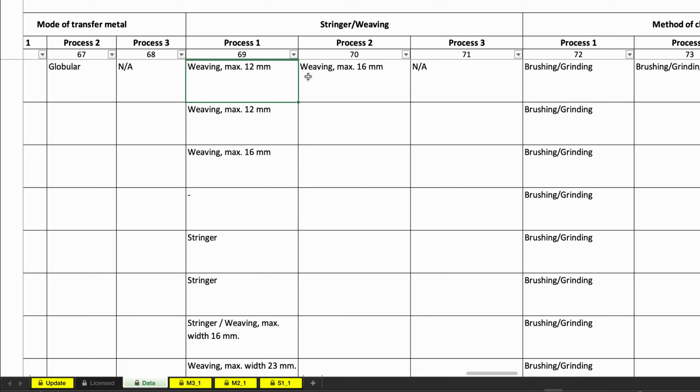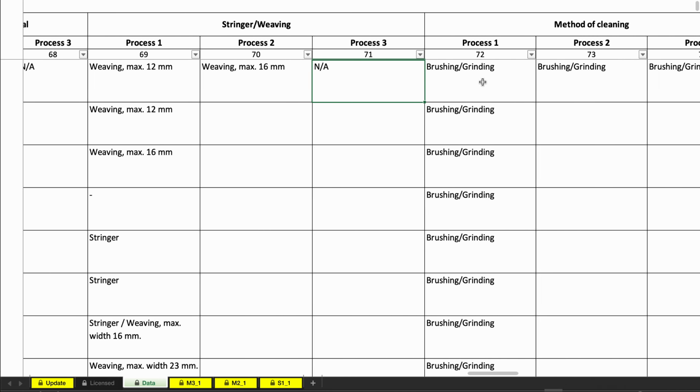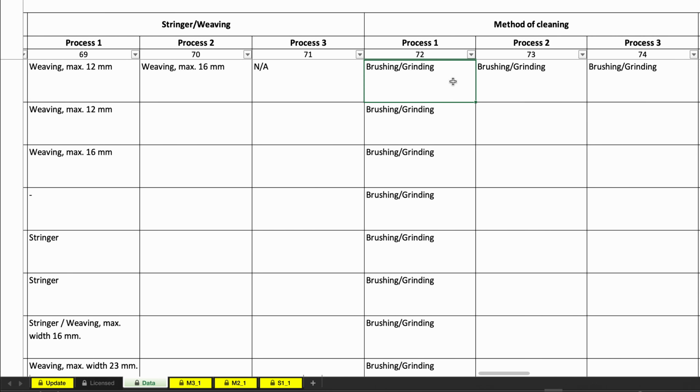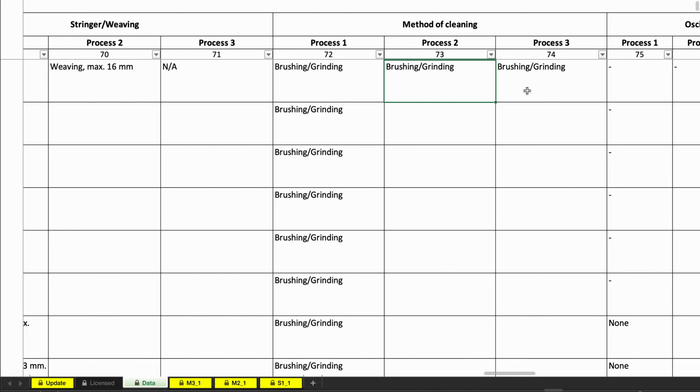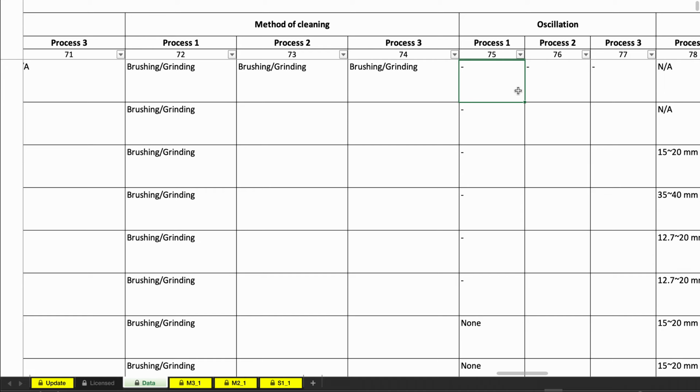Almost all information you get from your PQR during qualification, you take care by layer, width and depth of the pass to be applied. And cleaning methods during applying the next layer to be stacked here follow the same as your PQR qualification, almost using brushing or grinding, almost using brushing for today.